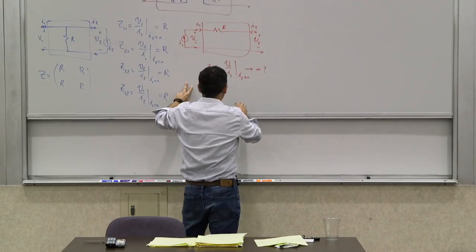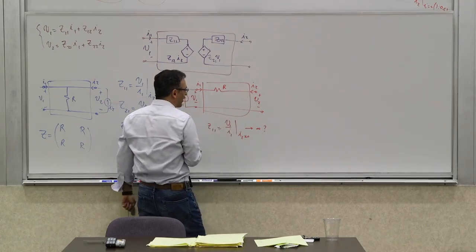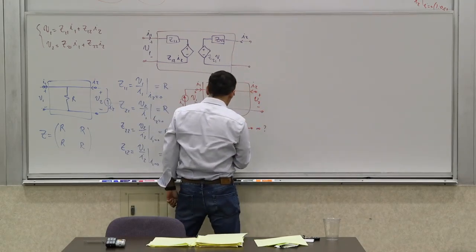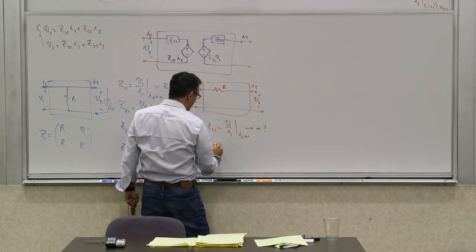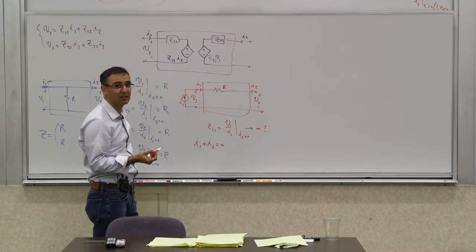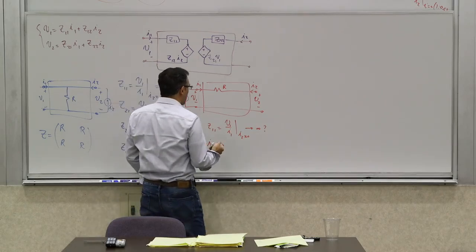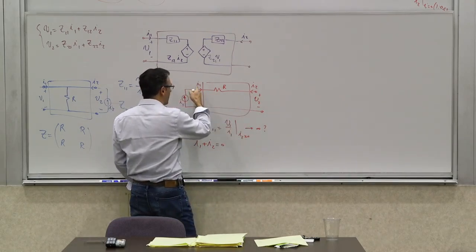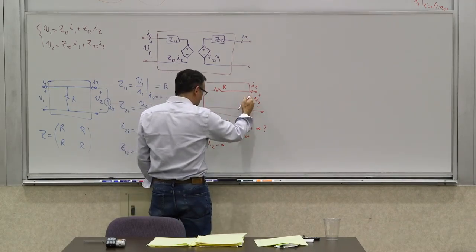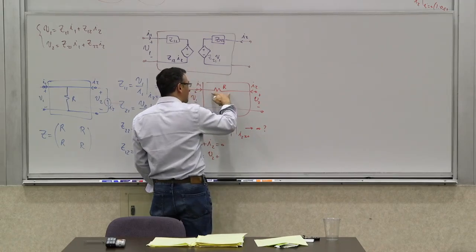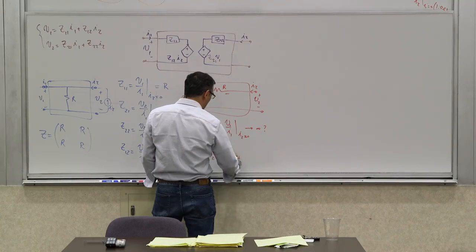So let's find out. There are two equations that describe this, right? What are those two equations? One is the relationship between I1 and I2. I1 and I2 are both going in, so the algebraic sum should be 0, because I1 and I2 are the same with opposite polarities. So I1 is negative I2. The other relationship is between V2, V1 and I1, or I2. So you can say V1, this voltage, is V2 plus the voltage drop across this resistor, which would be R I1.